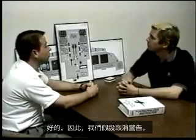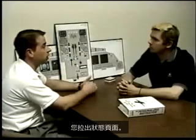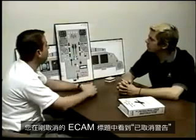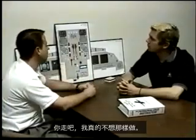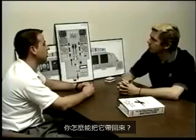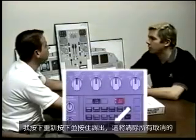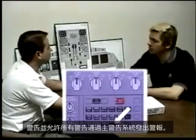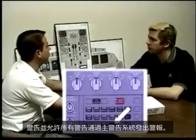Okay, so let's assume that we cancel a caution. Sure. Everything goes back to normal screen configuration. You pull out the status page, you see canceled caution and the title for the ECAM that you just canceled by selecting emergency cancel. You go, I really didn't want to do that. I want to run that ECAM. How could you bring that back? I'd press and hold recall, and that will clear all the canceled cautions and allow all cautions to then be alerted through the master caution system.